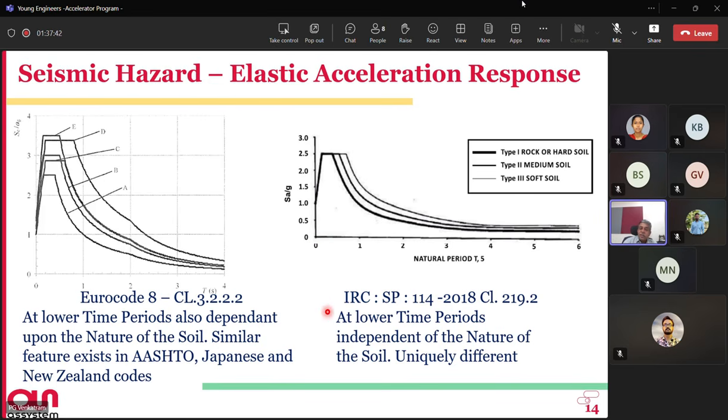That is the reason why the code says that if you are using elastomeric bearing as isolation bearing, no response reduction is applicable. Please remember, I can use elastomeric bearing as non-isolation also by introducing other restraint devices, which will make it equivalent to pot and PTFE. It all depends upon your detailing. That is why no response reduction is applicable for structure designed with elastomeric bearing as isolation bearing.